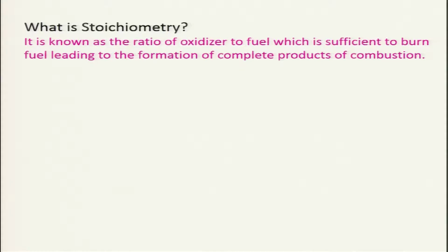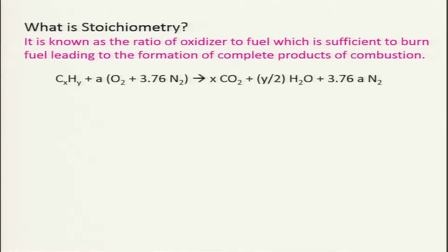Of course, this is the theoretical oxidizer fuel ratio, but in reality you need to give more oxidizer per unit fuel to have a complete combustion. So, let us look at 1 mole of CxHy. This is basically a generic hydrocarbon.